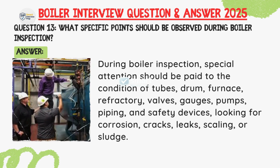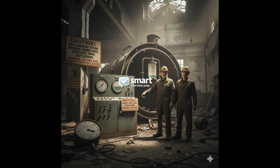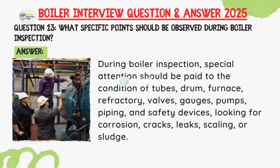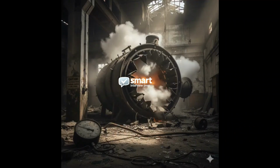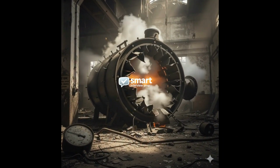Question: What specific points should be observed during boiler inspection? Answer: During boiler inspection, special attention should be paid to the condition of tubes, drum, furnace, refractory, valves, gauges, pumps, piping, and safety devices, looking for corrosion, cracks, leaks, sealing issues, or sludge.